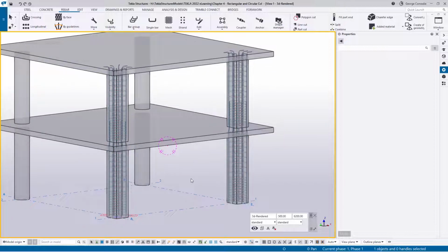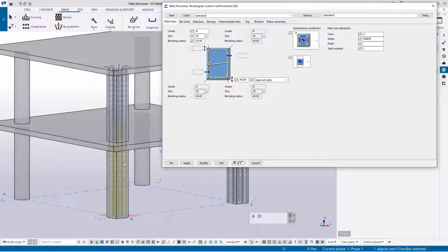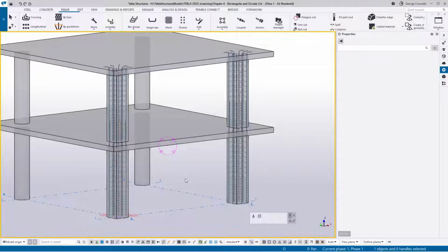I mean, normally in buildings like this, you can suffice with something like this, and you can save that away. If you double click on this and you know you've got this as a type A or type B or whatever, or a type 81 column, whatever you want to call it, you can save it away here and just call it up whenever you need it once the save is set. So it's a very, very quick way to model a building and to detail a building is using components. And in this case, they are definitely recommended.